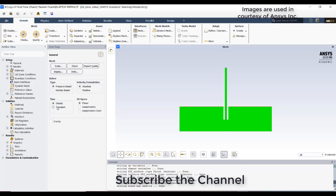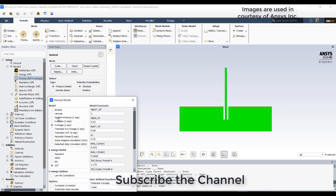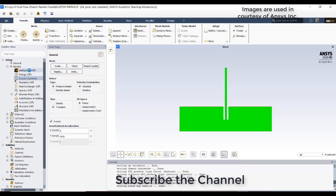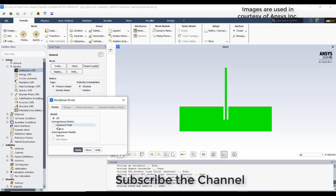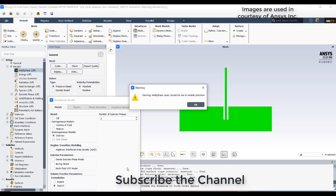I'll activate the transient mode, click on gravity, and set it to minus 9.81. In the materials, I'll just assume it is a laminar flow. Next, activate multiphase. You can go for a volume of fluid also, but I'm just going with the Eulerian model, which is much more accurate. It is due to the accuracy only, nothing else.